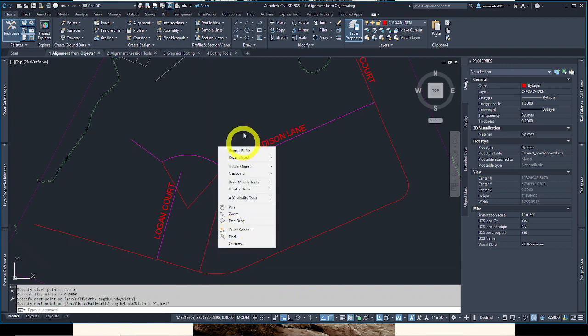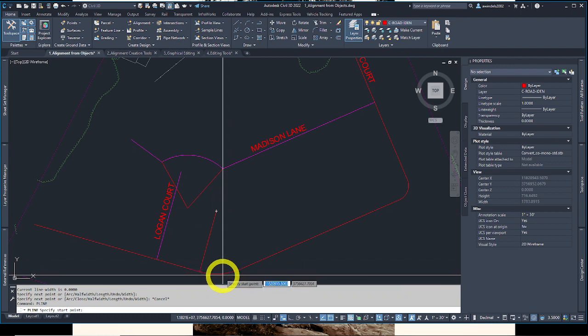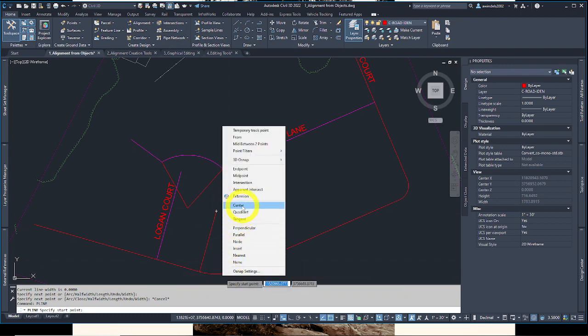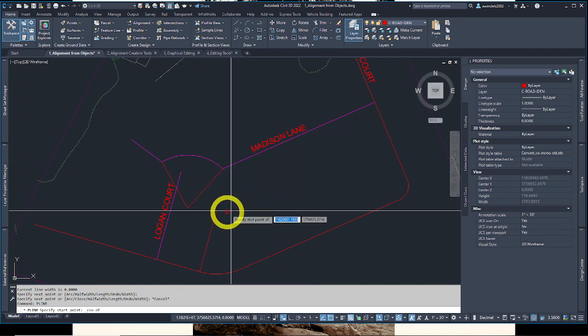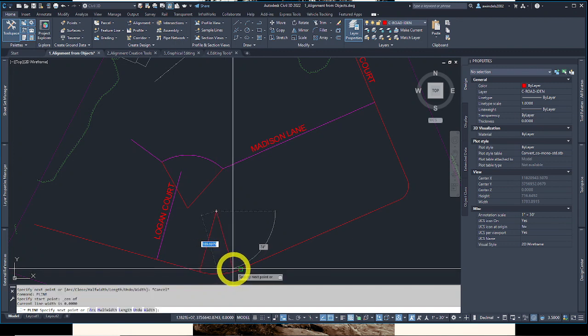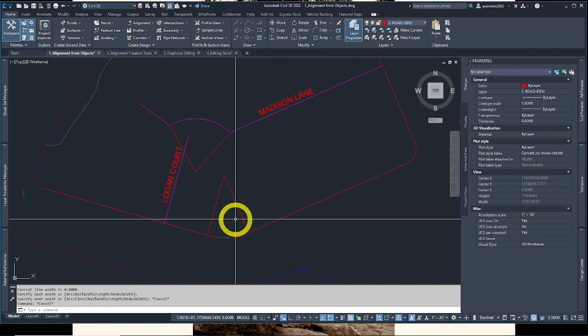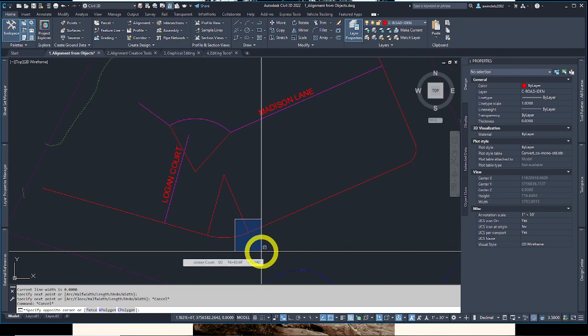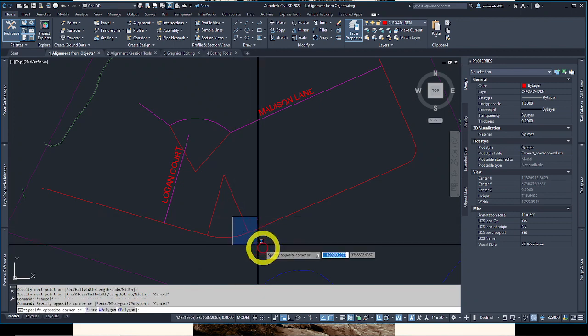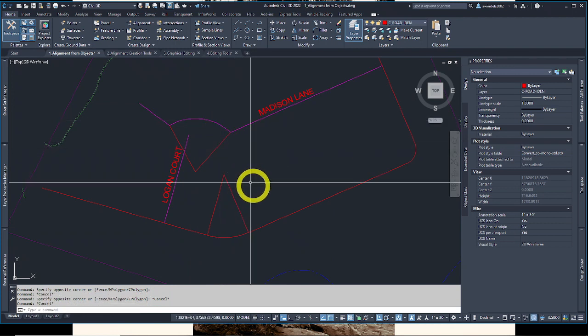These are tangent. I'll go to the center. If I hover on this arc, I'll right shift hold just to get center, just for one command. I'll hover by the arc or the curve. See that grip pulled up, and now I got the endpoint. So a tangent would have common degrees here. This would be 90 degrees. 90 degrees. This is definitely not 90 degrees. So I'm moving things around differently.